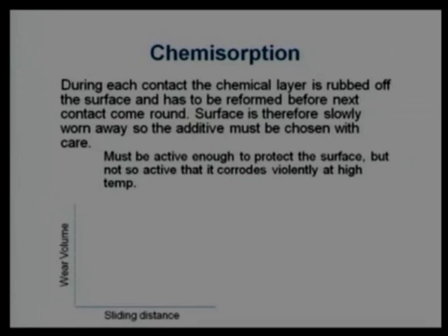Now, let us compare dry lubrication, boundary lubrication by physical absorption, and chemical absorption. We can compare them on a wear and sliding distance chart. We studied the wear rate. We know that as the sliding distance increases, total wear volume will increase.